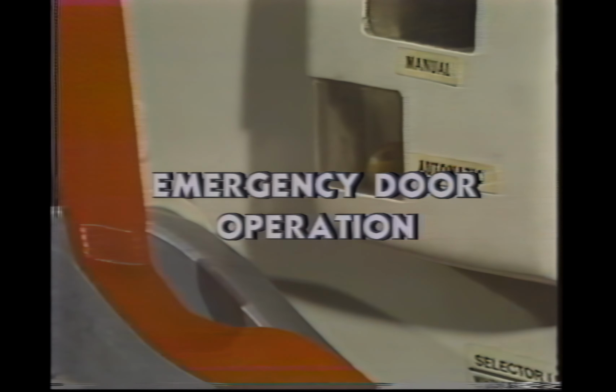To deploy a slide raft in an emergency, first evaluate the outside conditions. If outside conditions are safe, rotate the door operating handle up and aft. Open the door in an aggressive and forceful manner and push the door out until the power assist takes over. If the slide raft does not inflate automatically, pull the manual inflation handle located on the slide raft girt.